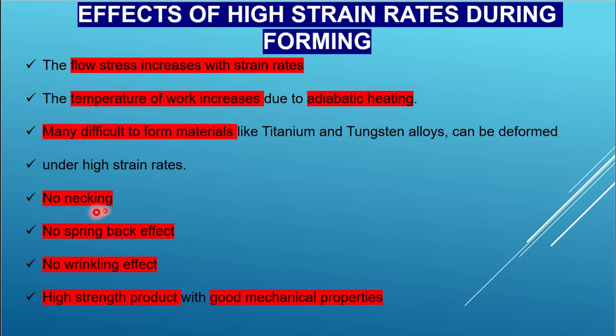No spring back effect. What is actually spring back? Spring back depends upon the elastic modulus. Elastic modulus is basically stress divided by strain, so that specifies the amount of elasticity of a material, right? So depending upon the elastic modulus, many materials after deformation try to recover back. So there will always be a small amount of recovery after deformation.